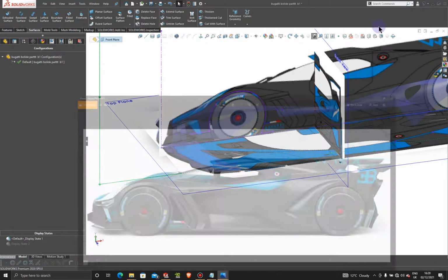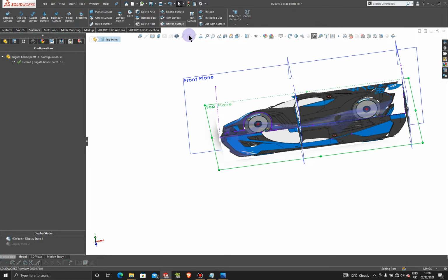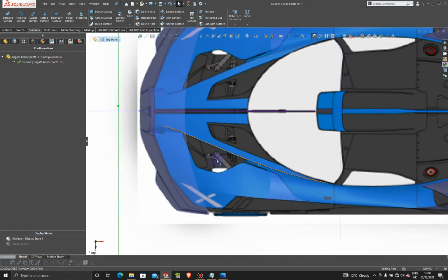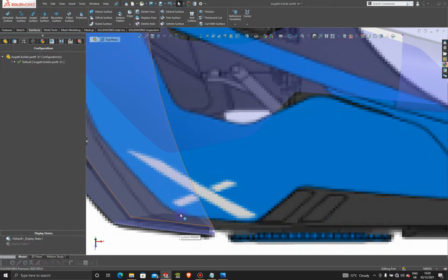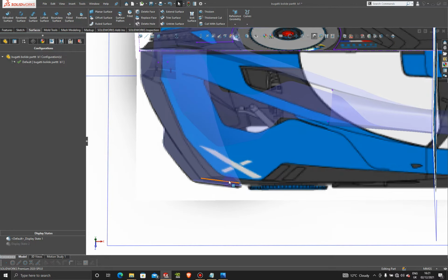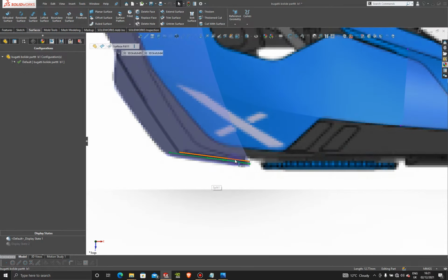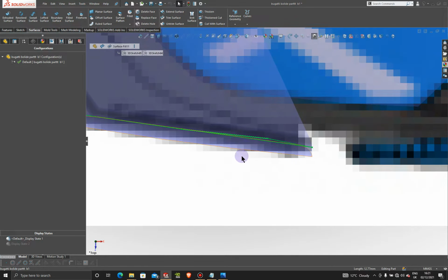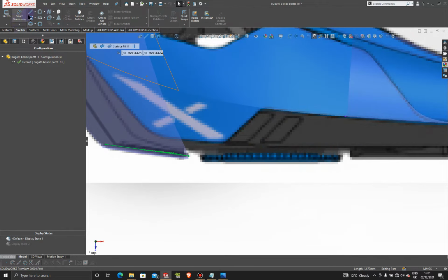All right, so the second sketch we're going to create is going to be on the top plane, normal to profile. And then let's just highlight this one edge here, not the whole thing, but that's fine. Highlight that one, press space bar on your keyboard so the highlight stays. So that's the upper line here. That's what we're going for, right? Okay, so let's start with a spline.